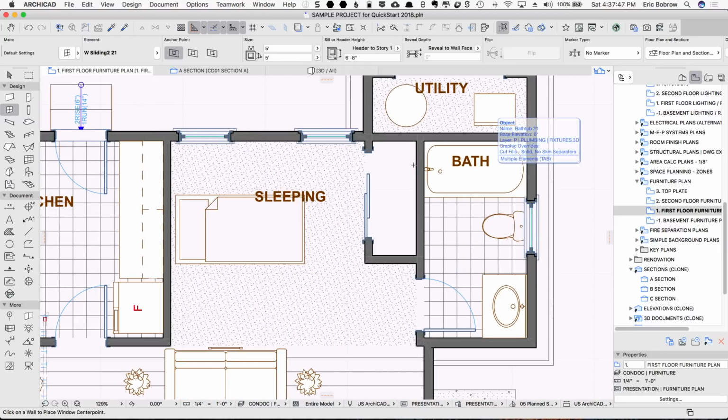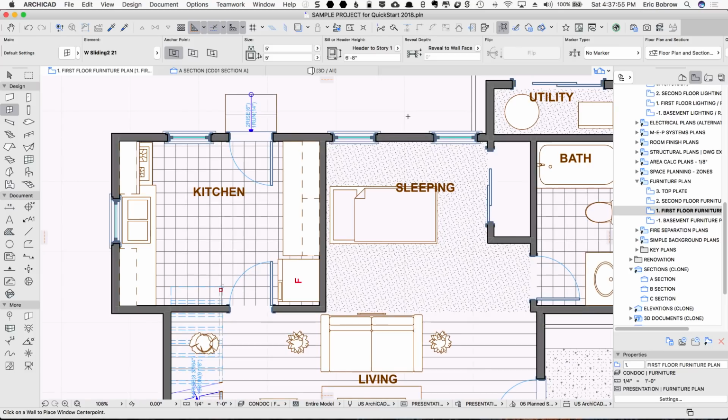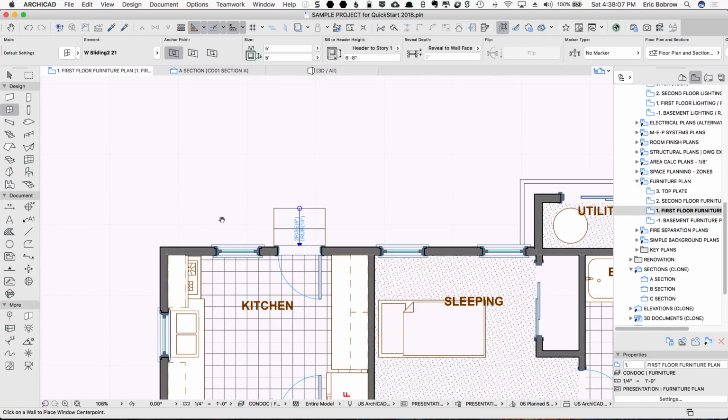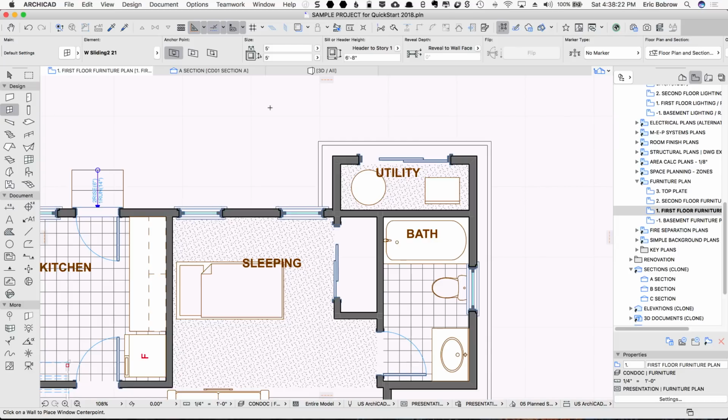Now if you want to slide over a little bit, you can press down the center mouse button, the mouse wheel, and drag. So press, drag, and release will move it. If you're on a laptop, you may need to actually use the pan tool, where you click on that, press down, move to the new position, click again. So basically the pan tool can be used on a laptop or of course on a desktop computer, but it requires some extra clicks compared to just press and drag, which is what's happening with the pan.